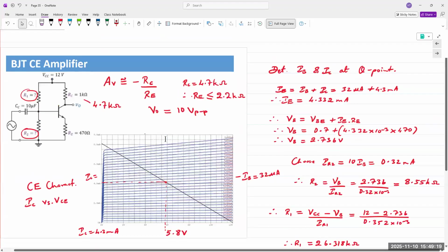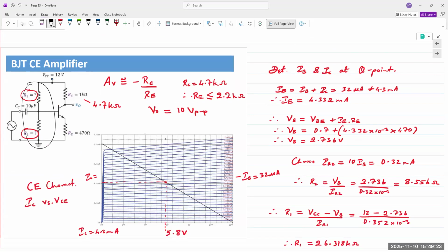All right, so here we have a circuit that has 4 resistors, R1 and R2, sometimes also known as RB1 and RB2, because they are the base resistors. They form a voltage divider, and hence this biasing circuit is also known as a voltage divider bias, which is again something we'll learn later on in a couple of classes.